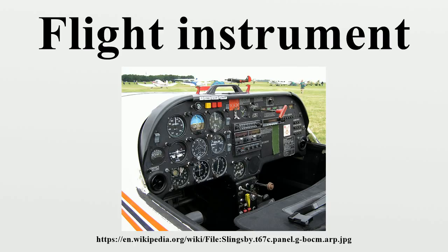The term is sometimes used loosely as a synonym for cockpit instruments as a whole, in which context it can include engine instruments, navigational and communication equipment. Many modern aircraft have electronic flight instrument systems. Most regulated aircraft have these flight instruments as dictated by the U.S. Code of Federal Regulations, Title 14, Part 91. They are grouped according to pitot static system, compass systems, and gyroscopic instruments.